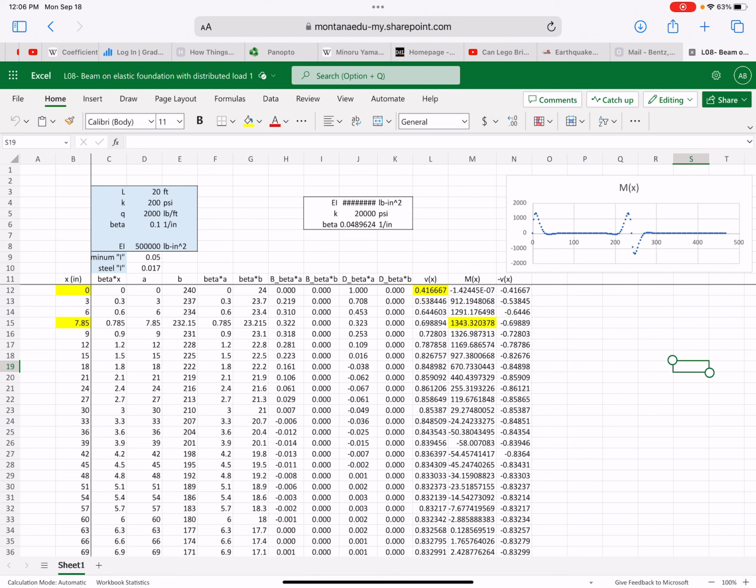Well, if you calculate that out, just for context, the EI we calculated was this value, and if you factor out the magnitude of E, Young's modulus for aluminum, which is roughly 10 times 10 to the 6, you end up with a moment of inertia of about 0.05 inches to the fourth, which is really small, right? And for steel, it's even smaller. So we're talking about a really small, really flexible material here.